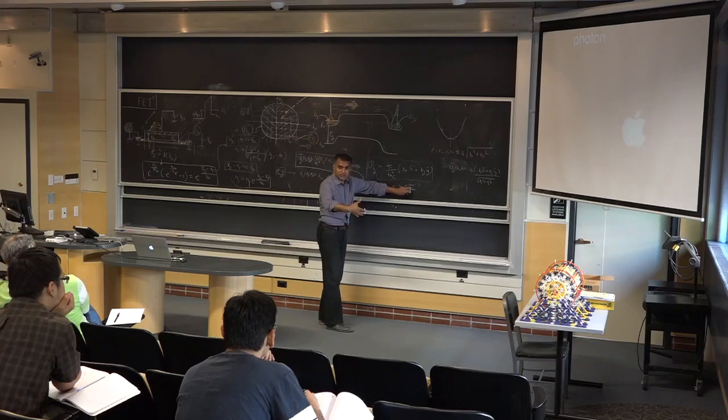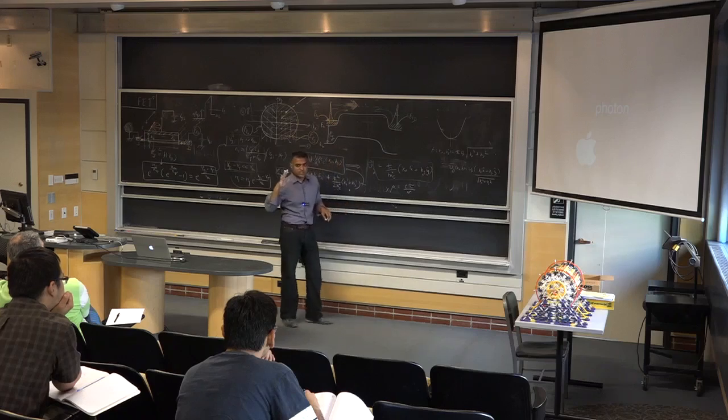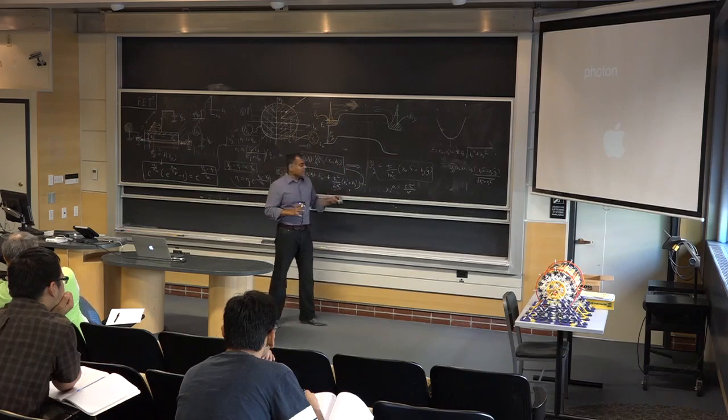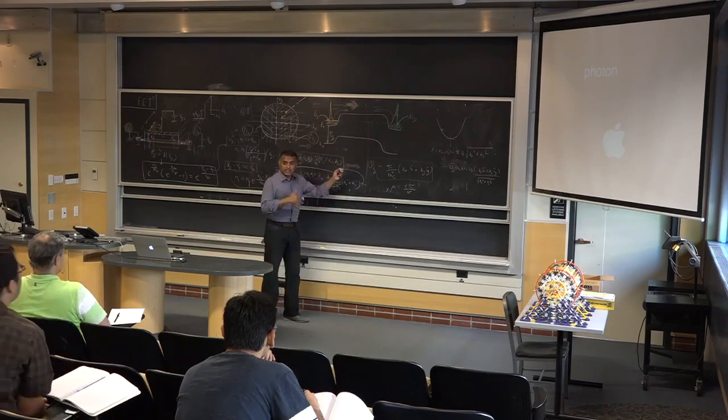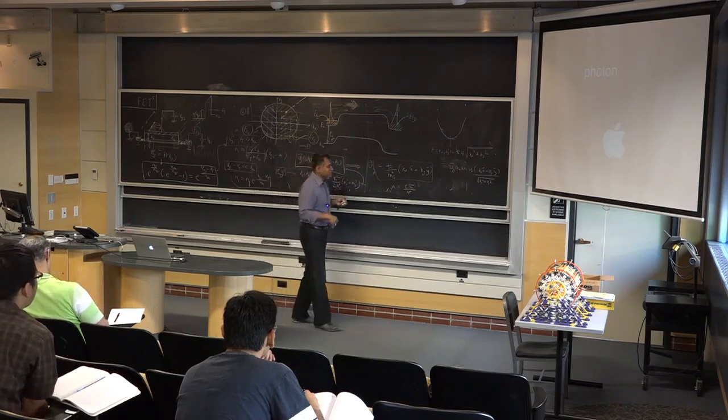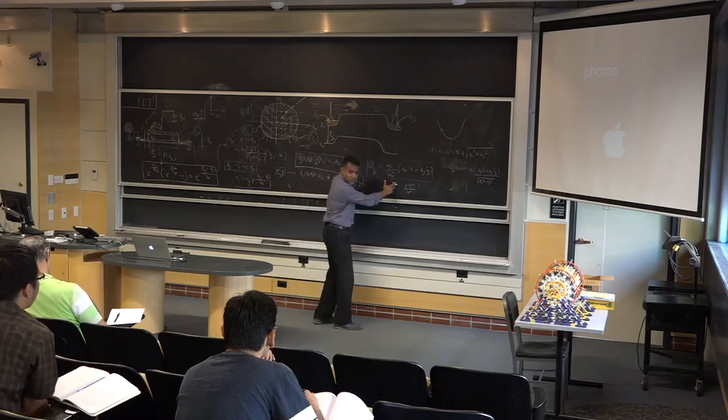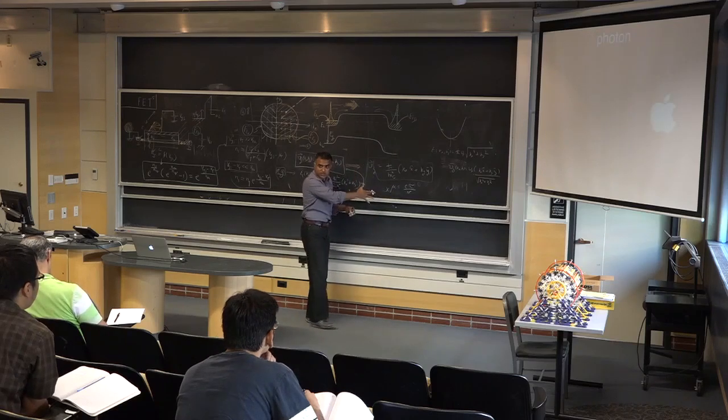But in the limit of completely pure material where there's no scattering, you don't have a concept of mobility. That concept is wrong. So we are going back to the roots and saying, what will happen if there's no scattering at all, right? And that's what we're answering now. And hopefully with time, I'll connect it to the picture where we have the mobility and drift diffusion once we are done with the quantum picture.